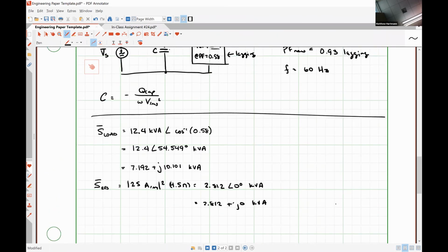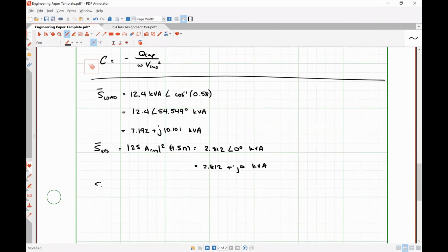So from these two pieces of information, we can now determine how much complex power our source is supplying before power factor correction. Does anybody have any problems with that statement? No, sir. What I'm saying is that the complex power supplied by the source is the exact same as the complex power absorbed by our resistor plus the complex power absorbed by our load. And this is true before power factor correction.